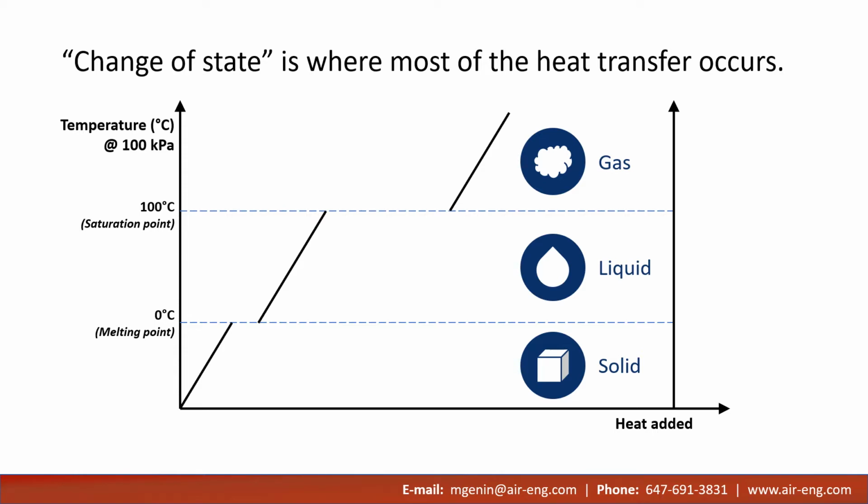For this presentation, when we say refrigerant, let's keep it simple and just think of water. In the refrigeration process, the water will exist as a liquid or gas. We won't talk about it existing as a solid because that will cause major issues for what we're trying to achieve. When heat is added, the temperature of the liquid rises, and once it reaches its saturation point, it begins to boil or evaporate from a liquid to a gas.